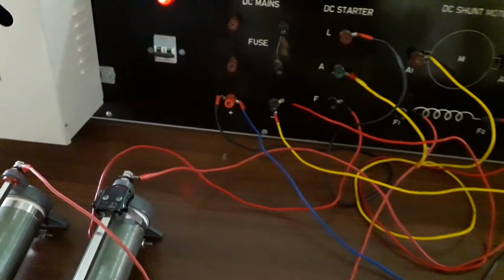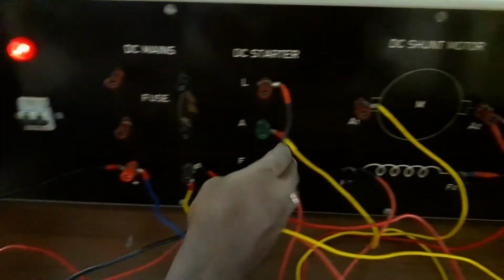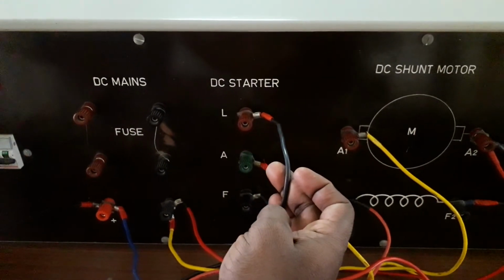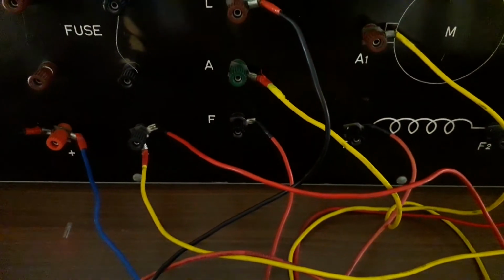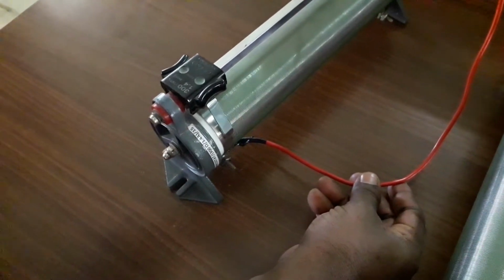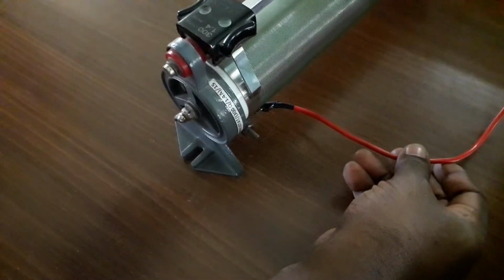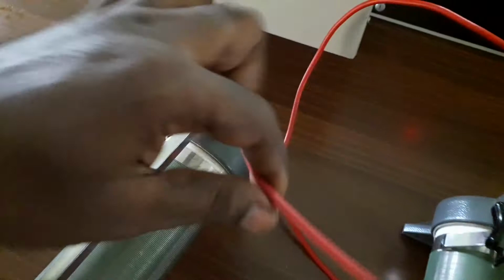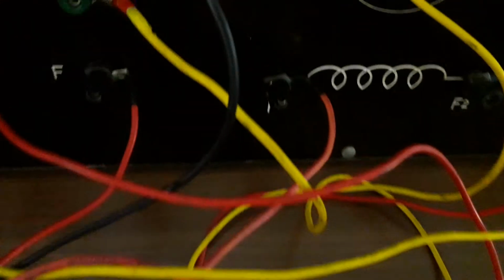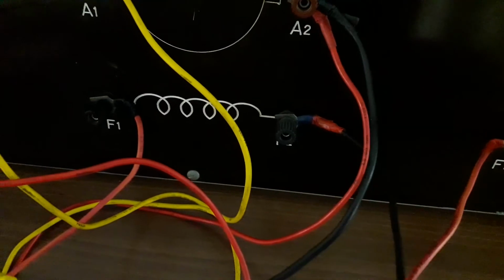So first, from the positive terminal, the wire is connected to your L. Then from the field terminal of your starter, the wire is given to your 300 ohm 1.4 ampere rheostat input. The slider is near the input, so it is in the minimum position. From the output of your rheostat, it is connected to terminal 1 of the field winding. From terminal 2 of your field winding, so this field winding is the motor field winding,